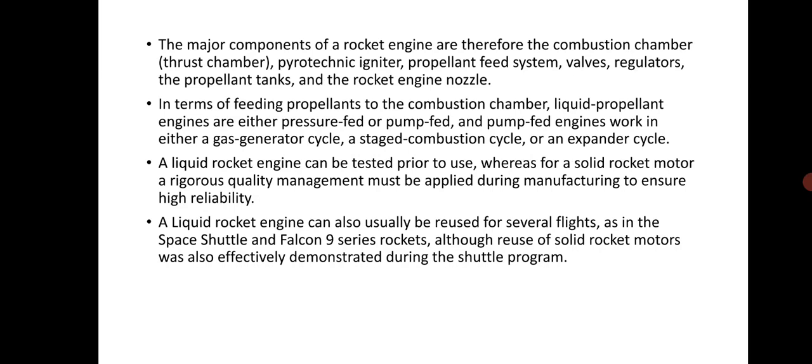In terms of feeding propellant to the combustion chamber, liquid propellant engines are either pressure fed or pump fed, and pump fed works in either a gas generator cycle, a staged combustion cycle, or an expander cycle. A liquid rocket engine can be tested prior to use, whereas for a solid rocket motor, rigorous quality management must be applied during manufacture to ensure high reliability.